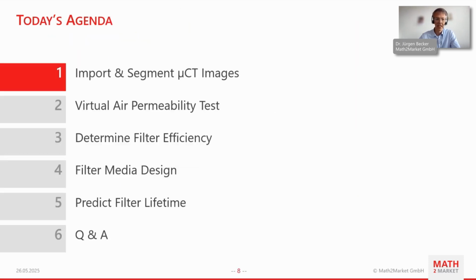So today's agenda is that we will first import and segment the microCT images of this sample. We will then run a virtual air permeability test and determine the filter efficiency of this material. Then we will have a look on how to change the filter media design and give an outlook on how to predict the filter lifetime.